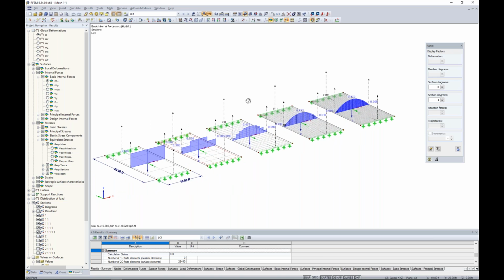Now, how do we check this for our own structure? Well, we can just manually refine the mesh, run the calculation, take a look at our results. Let's rerun the calculation with a more refined mesh. Are our results drastically changing? Yes. Well, then we need to continue refining until we get to a point where the results are not changing much, and then we can probably move forward with our static analysis.